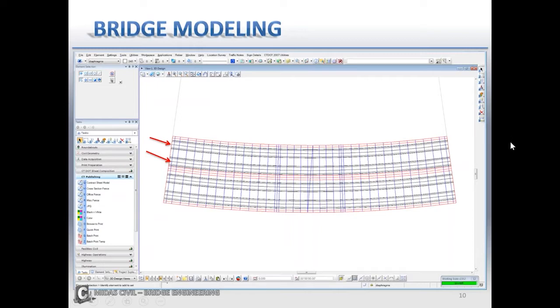Then I offset this baseline to all of my locations where the center of the girders would be, as you see in red here, which you can typically find this distance in the framing plan. I also offset the baseline to reflect the deck edges, basically the out to out, these two red lines here. Here you can see them, and here's all my center lines for girders, this one, this one, this one, and this one. And I also use the radius of the bridge to generate the lines that represent where all the cross frames would be, as they are perpendicular along the curve.